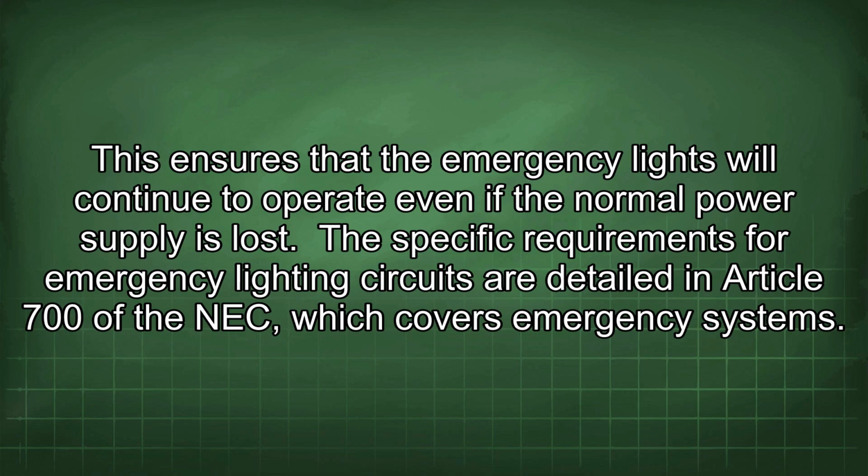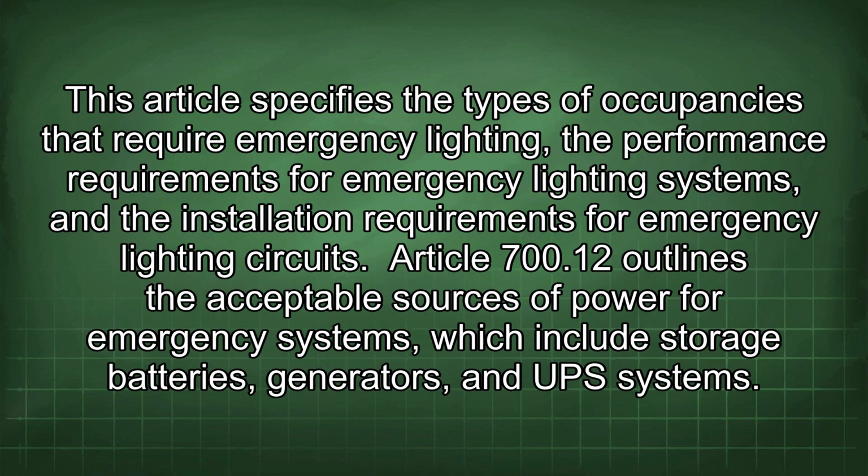The specific requirements for emergency lighting circuits are detailed in Article 700 of the NEC, which covers emergency systems. This article specifies the types of occupancies that require emergency lighting, the performance requirements for emergency lighting systems, and the installation requirements for emergency lighting circuits.